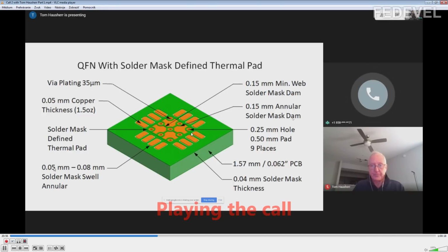That's where it gets interesting. You actually put solder mask over the part where you see the pattern. That's the solder mask pattern. So that will be like 100% solder mask of this specific area? Well, no. The solder mask you see here is the green. Sorry, the paste would be 100% of this uncovered area on the exposed part.